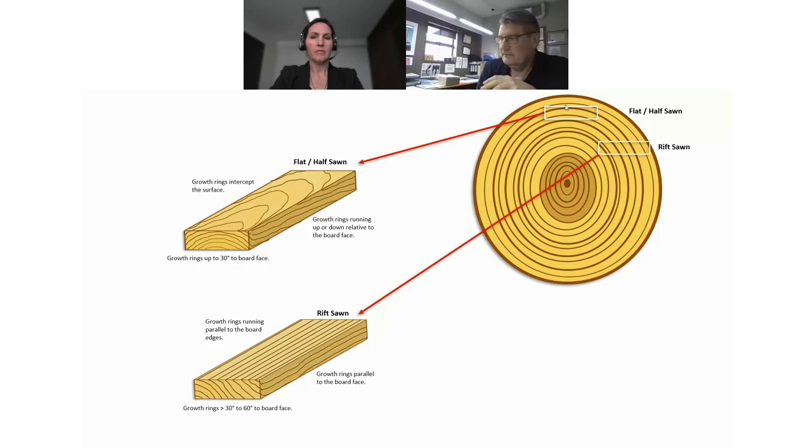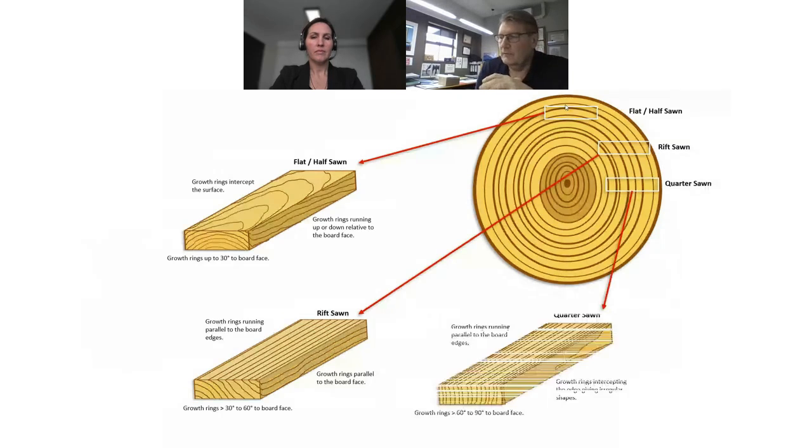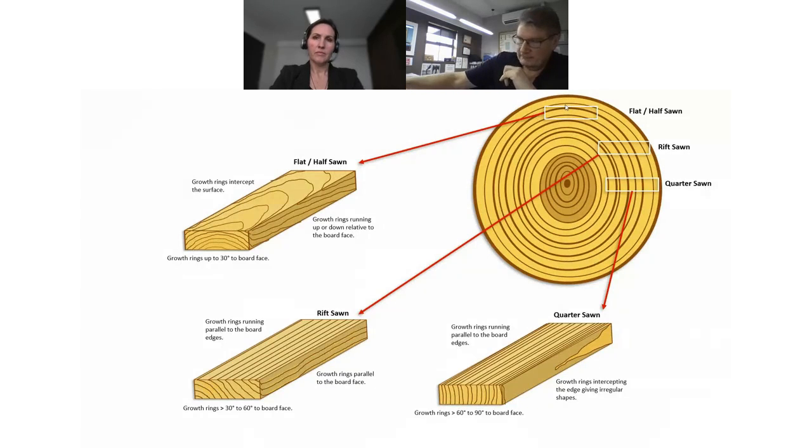And my favorite is quarter sawn. With quarter sawn, you see the growth rings basically up and down at the end and striped along the top, and you only get the cathedral effect down the side. It's no big deal on that. As far as I'm concerned, between half sawn and quarter sawn for today's presentation, quarter sawn is, regardless of the timber, always more stable, and that will make sense in a minute. So that's the sort of thing you're looking at. Again, remember, this is 101 of timber. So there you go.